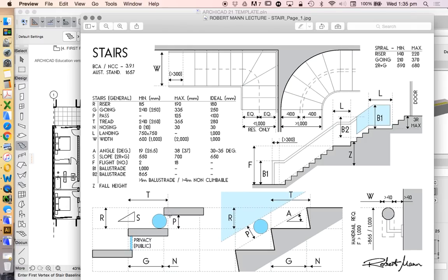So whether it's a step, whether it's a bit that hangs out, we could call that a cantilevered end, or whether that's an angled, and we more commonly see this on a concrete stair, it's both nosing. Now this one's probably a little bit safer, less ability to get your toe caught or bash the back of your heel if you're walking down the staircase.